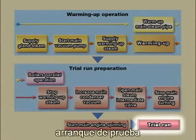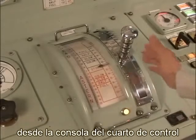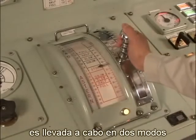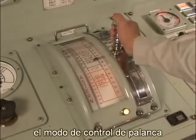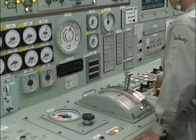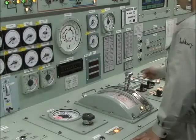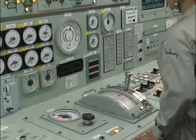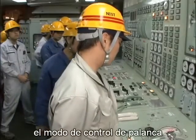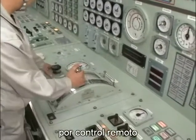Trial run. Main engine trial run from the control room console is carried out in two modes, the lever control mode and the direct switch control mode. Lever control mode is a method to manipulate the maneuvering valve electrically and hydraulically via remote control.